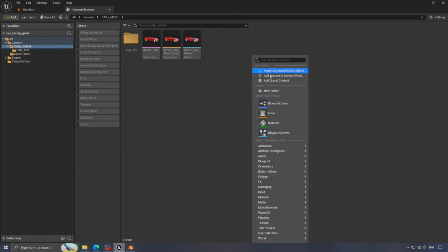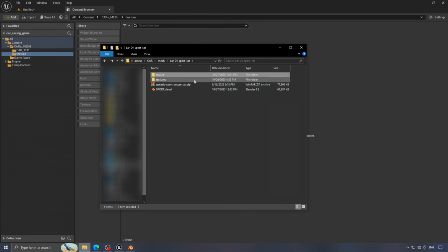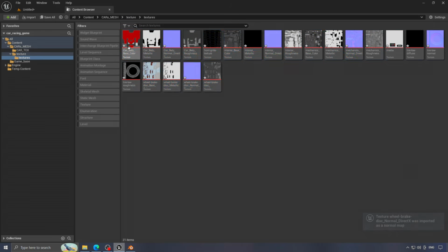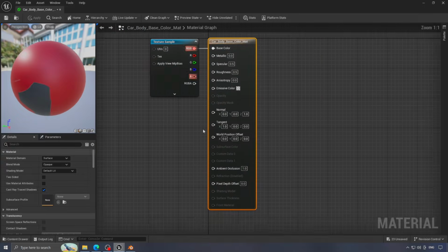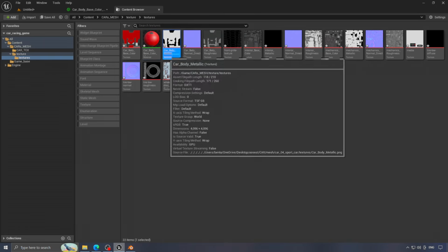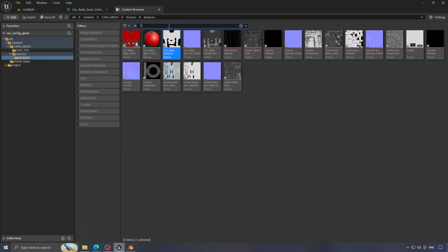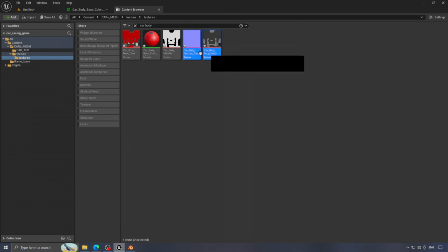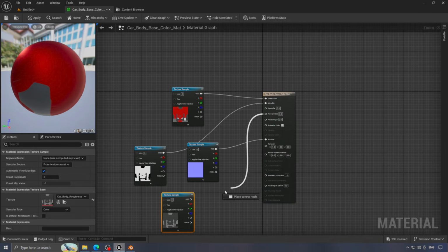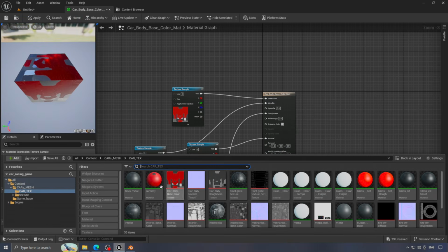As for the second one, it's based on importing only the car textures separately and then creating the materials ourselves. We'll rely on the names that come with the texture files and link them properly. Once done, we'll assign each material to its corresponding part.